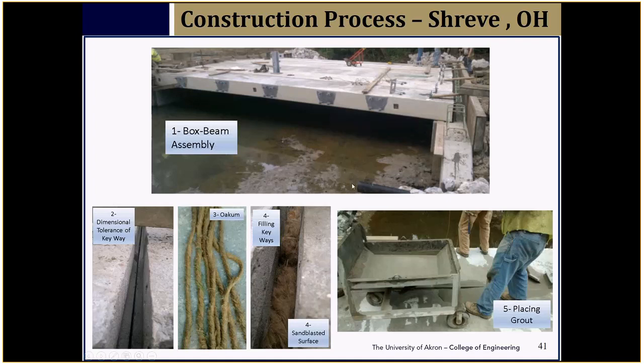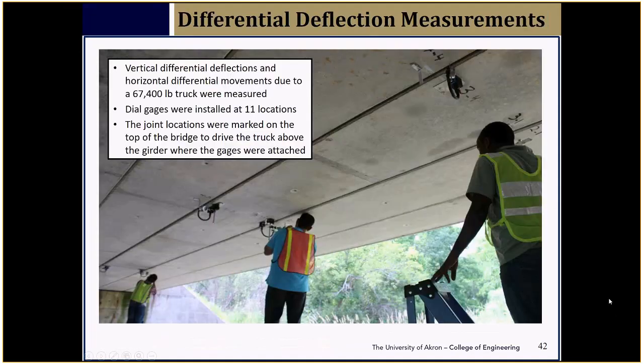And what they do is they actually add water until the grout is fully flowing. That's the way they see it. Okay, so they don't see the structural aspects of the grout, but they just look at grout as a filler material. So they just fill it and then keep going. And the bottom is sometimes not properly sealed. Therefore, you will see a lot of grout going into the stream. In this case, there is a stream below that. So it goes into the water. So that's a big problem.